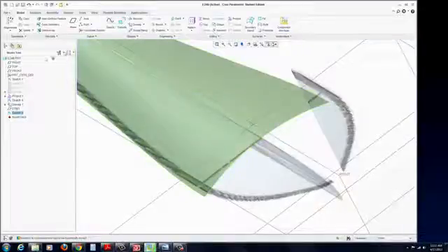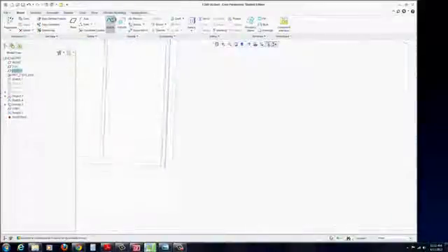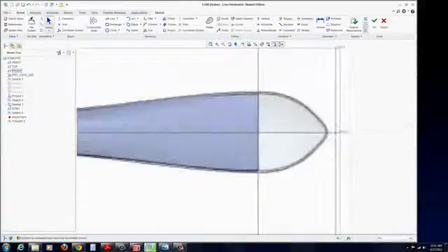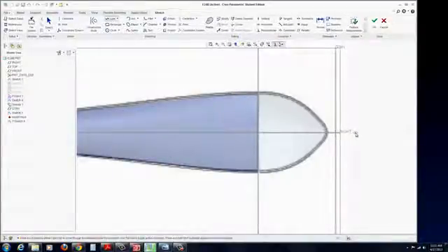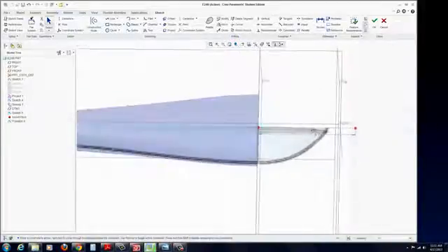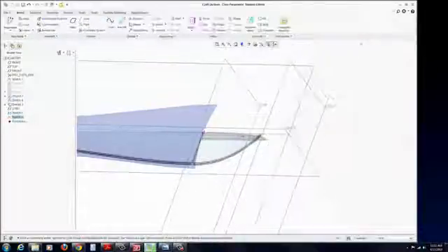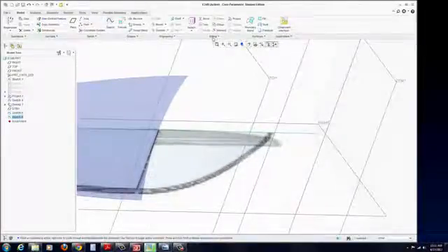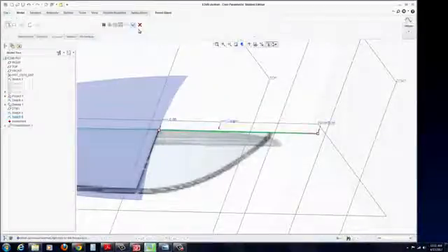And now you're going to have to select the front plane again, start a sketch, and just draw a line here to here in there, essentially for your trajectory. Okay, and now we should be able to go to swept blend. It hopefully picked your line that you just drew. If not, go ahead and select that. Make sure it's set to create a surface.